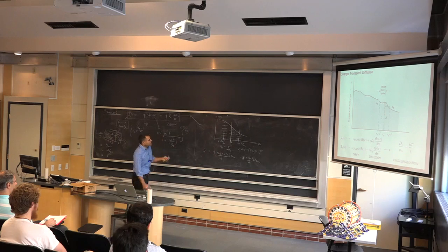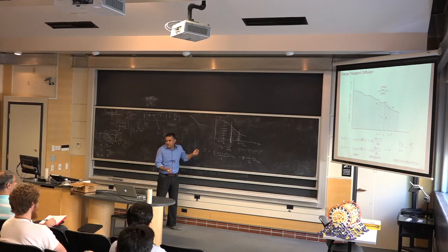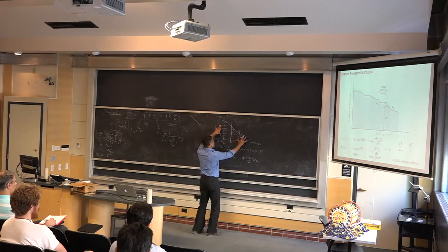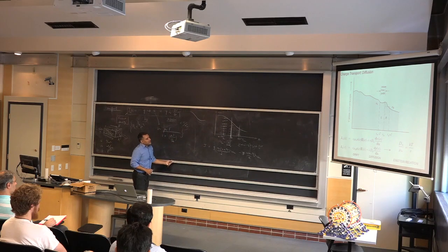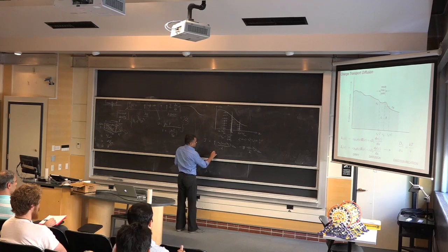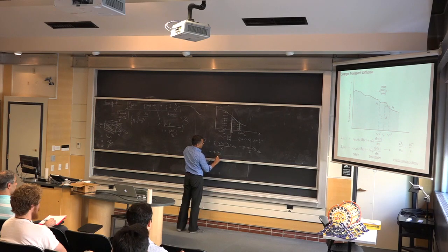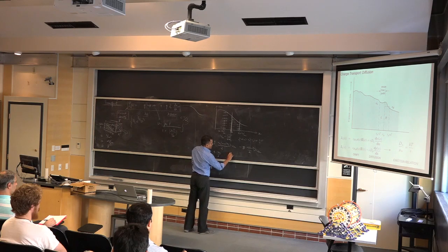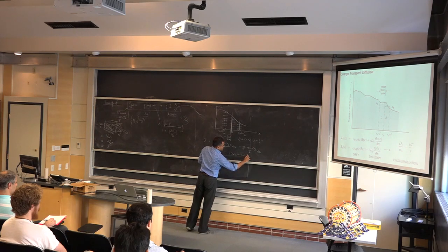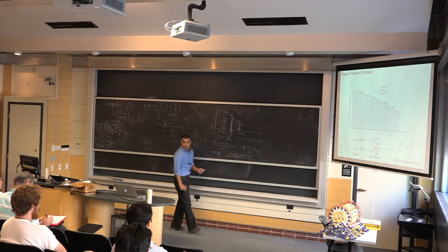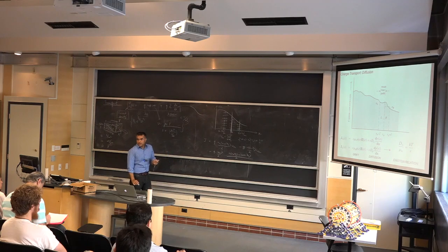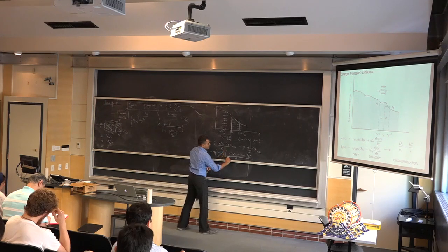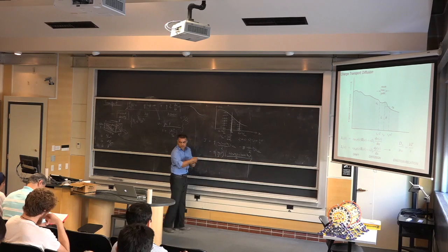So as you can see, I can now do a little bit of a change. So this is the current, and the sign you can fix. If I have more electrons here and fewer electrons here, electrons will go that way, so the current is going that way. That's the idea. You can do a little manipulation here and take out the thermal velocity and the 2's and write n of x plus lambda by 2 minus n of x minus lambda by 2, and divide the whole thing by lambda, the mean free path, and multiply by lambda here, so you club these together.